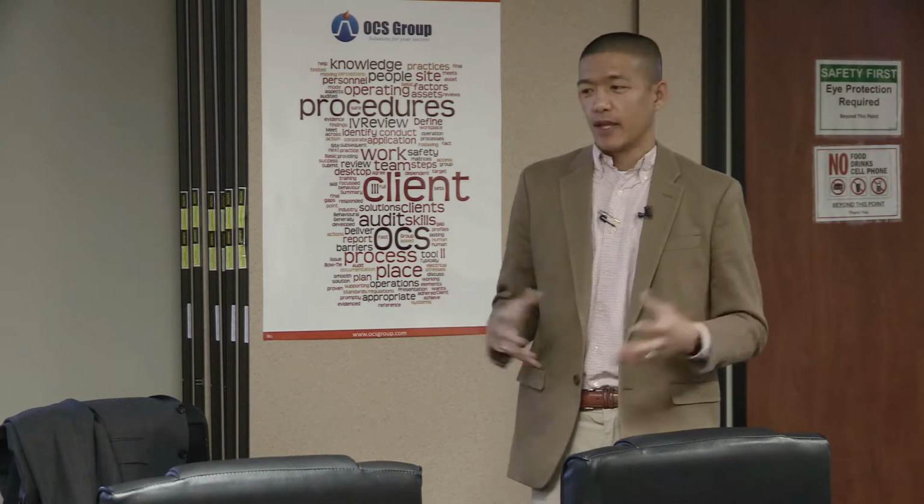And de-energizing the equipment right before you're about to do that infrared testing kind of negates the whole infrared test, because you want to see what the actual load is on the system and see how hot those points are on that piece of equipment that you're infrared testing. So although the 70E allows it, you still have to be suited up, even if the hazards are greater than what I consider to be the safest amount of 40 cals. They do permit it.